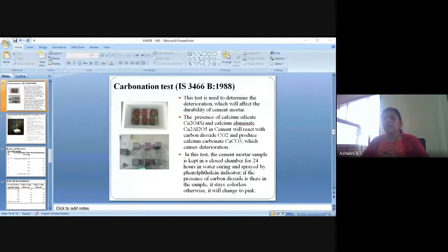And the next, chloride test. Here, after testing, we have calculated the chloride amount in terms of gram per meter. So for 0% it is 1.06, 10% 2.94, 20% it is 3.92, 30% 4.9, 40% 5.8, and 100% it is 66.95. So these are the conclusions.